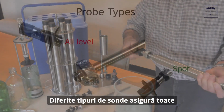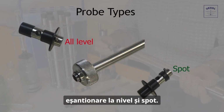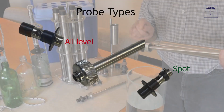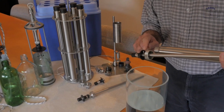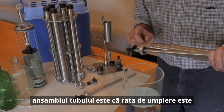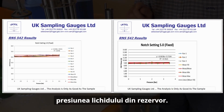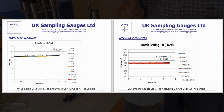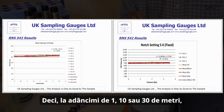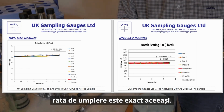Different probe types provide for all level and spot sampling. A distinguishing feature of the steel tube assembly is that the filling rate is not affected by the pressure of the liquid in the tank. So, at depths of 1, 10 or 30 meters, the filling rate is exactly the same.